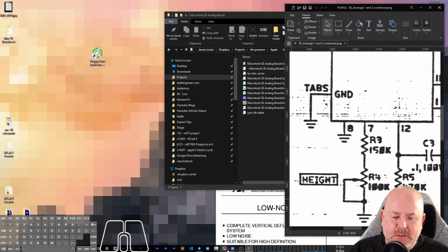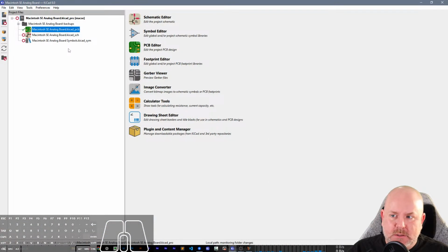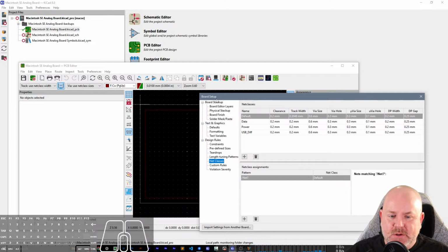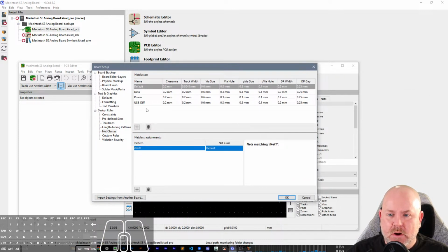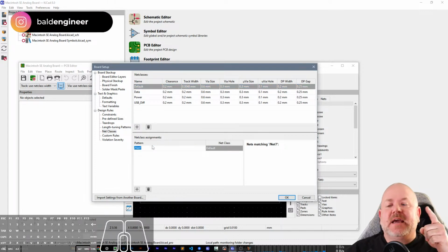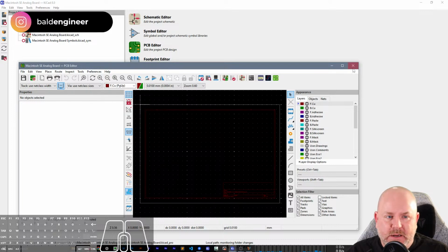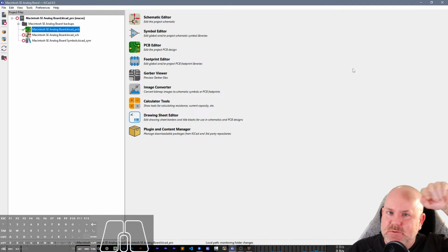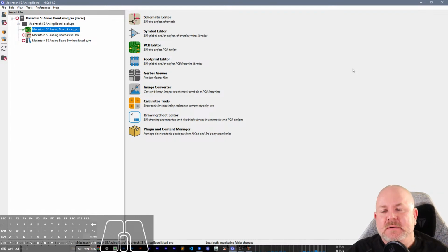If I go and look at PCB, and maybe you're just refining your question, and now I'm over-explaining, but just to demonstrate one more time. If I go into net class setup here, oh, in this case, they're not showing. Okay, shoot. All right, you know what? Never mind. I believe they're supposed to sync between them. It's not syncing right now because I have to do F8 to bring the nets into PCB so that PCB knows what the nets are.